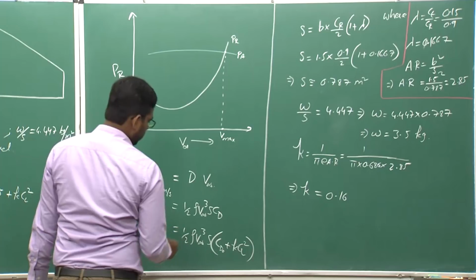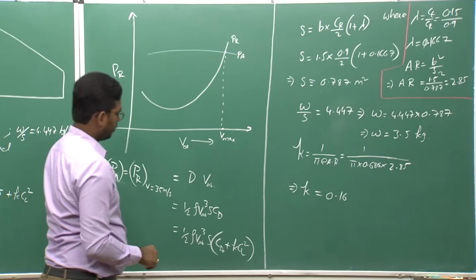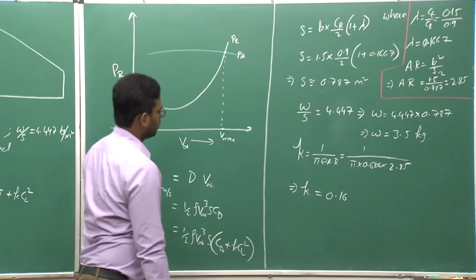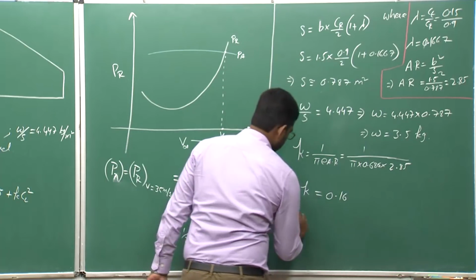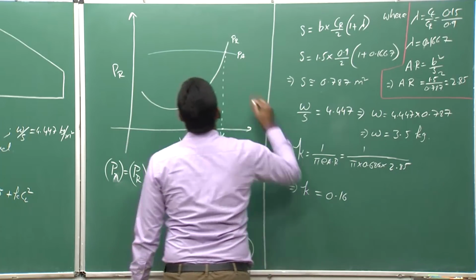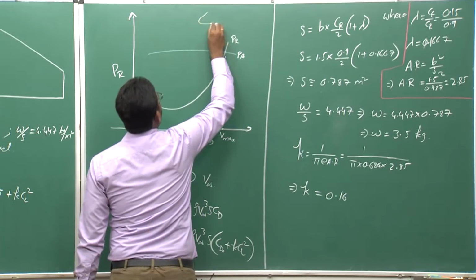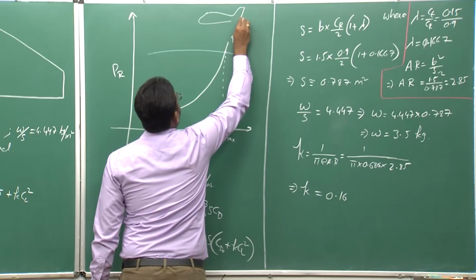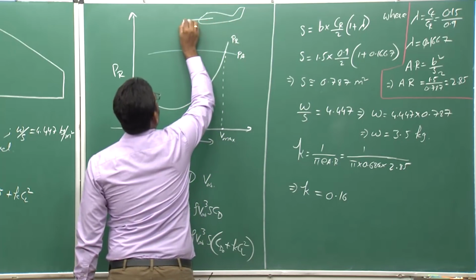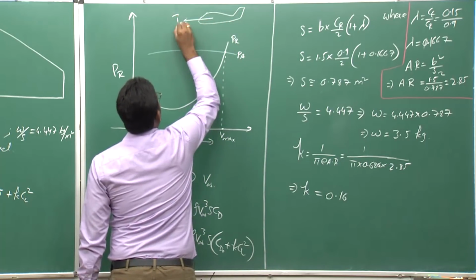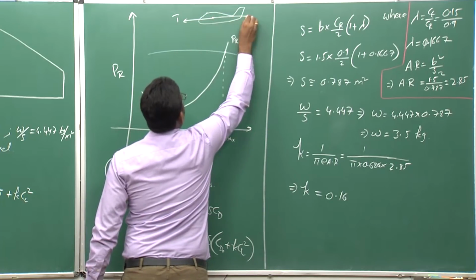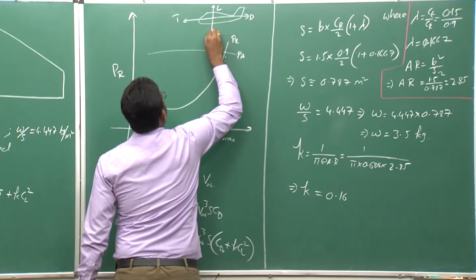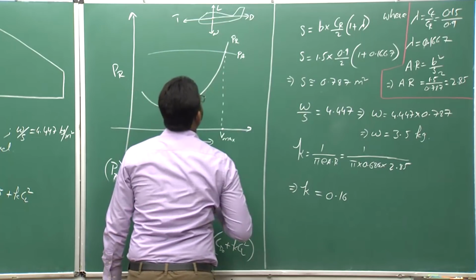Now, we have K here. Now, we need to find out the corresponding CL. How do you find CL? We have from equation C2, since it is level flight, right, we are talking about level flight. So, during level flight, thrust is equal to drag of the system and lift is equal to weight of the system.